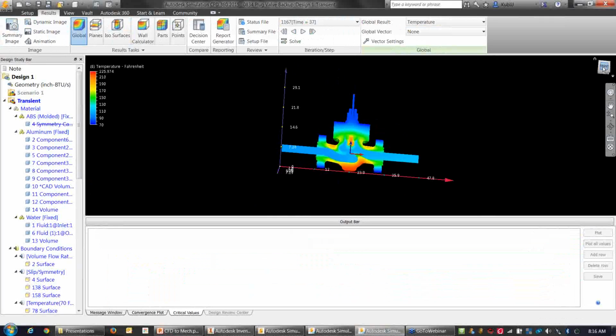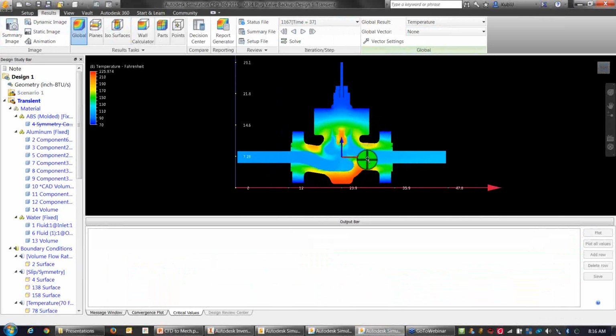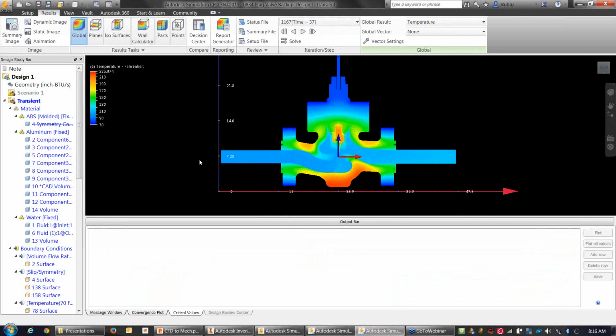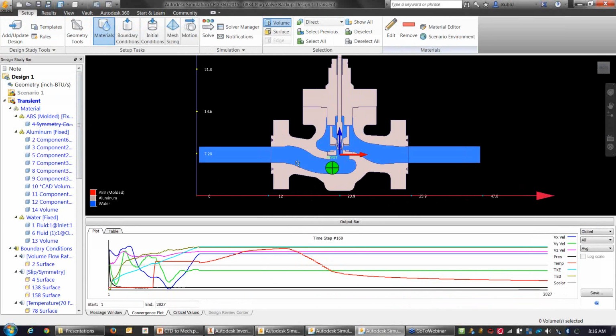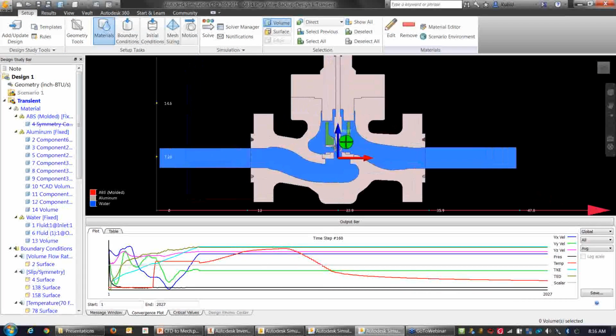here's our other analysis where we do thermal, and this is one of the major advantages of CFD. I've got a fluid flow through a valve. Let's hide this so you can see it better. So we've got fluid flow through a valve. The temperature of the fluid is much hotter than the temperature of our valve here, and there are thermal constraints or temperature boundary conditions on parts of the valve here that keep it cooler than the fluid flowing in.